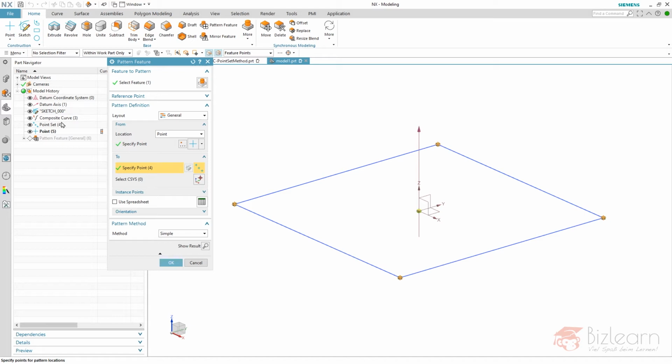Horizontal modeling means it's just one rule you have to follow. If you select something, always select the possible oldest objects. So what is old, what is new? I have a reference here to my feature points. I've created a feature by start a feature point set, and then I've created my points. So the points themselves are newer than the feature, and there's a relation to my point set itself, to the feature, to the possibly oldest element. That's the rule. Horizontal modeling means that if you have the chance, always select the possibly oldest object. That's it. This rule I'm following within this parts to maintain everything as stable as possible.